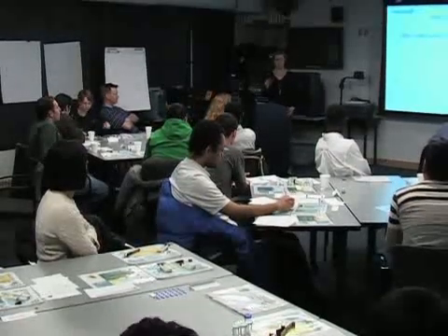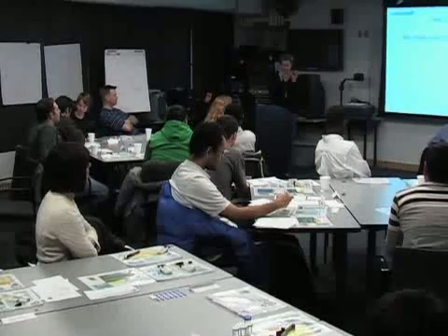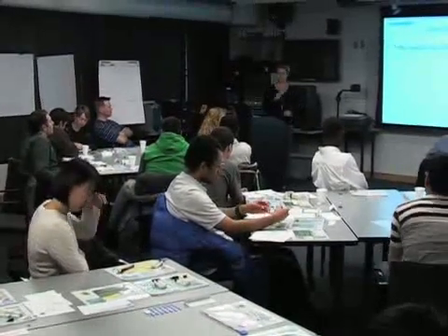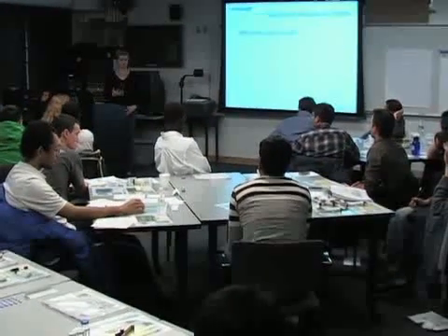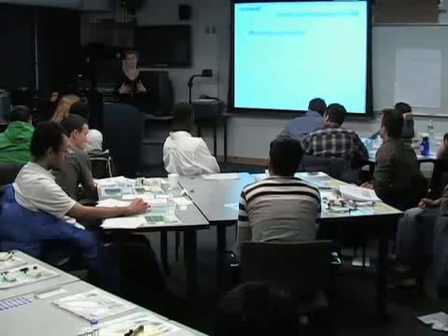If you're reducing the part count, each part has a specific tolerance to it. The more parts you add together, the bigger that uncertainty and potential tolerance grows. You have fewer parts, that comes down. What else? That is good. Fewer chances to make mistakes, yep. Because every part I handle has some probability that I'm going to make a mistake with it, and I have a few of those.